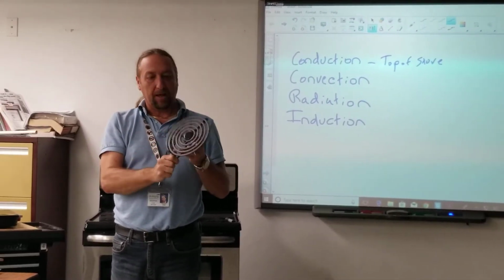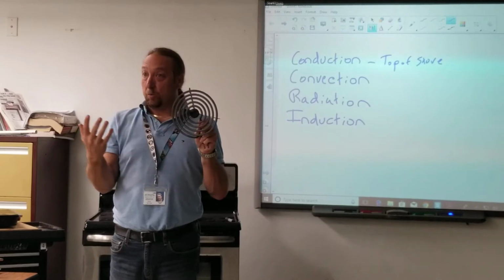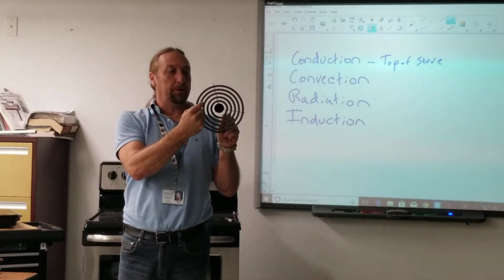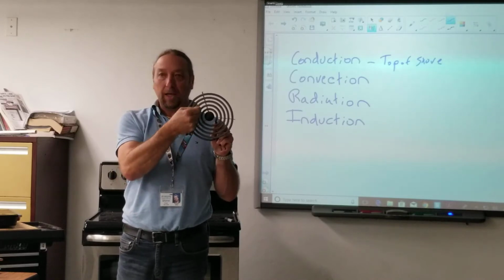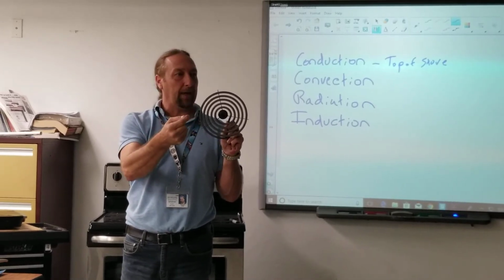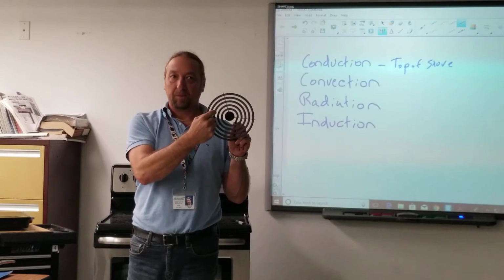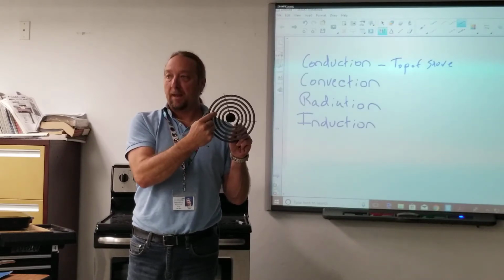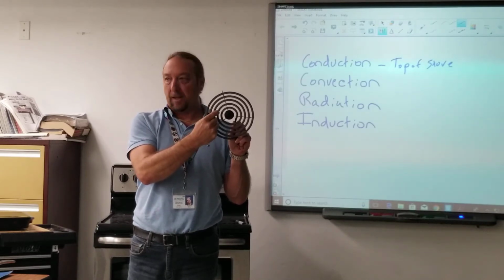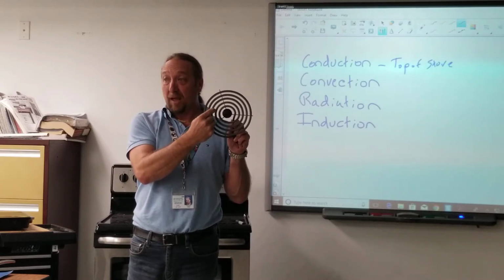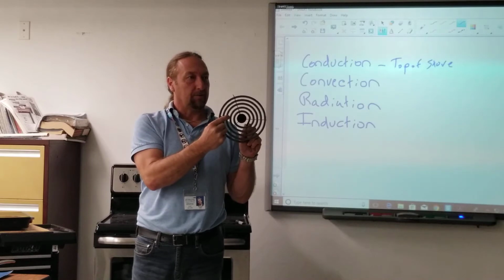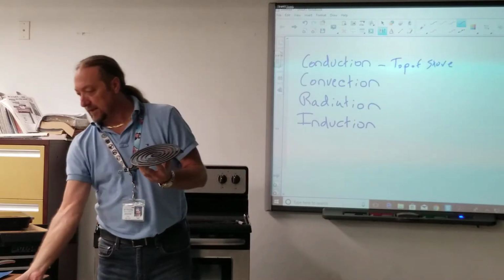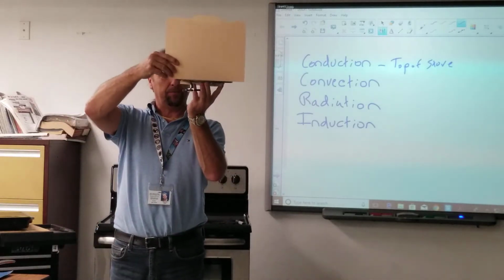The problem with an element like this is, like we say, conduction, but in between each one of these coils, there's a gap. And so there's no heat being transferred from here to your pan, so you got a spot that touching the bottom of your pan is creating a lot of heat. Then you have a gap to the next loop here, so you actually have a different temperature between here and here in that space. Now when you're looking at it, it has to be flat, okay?